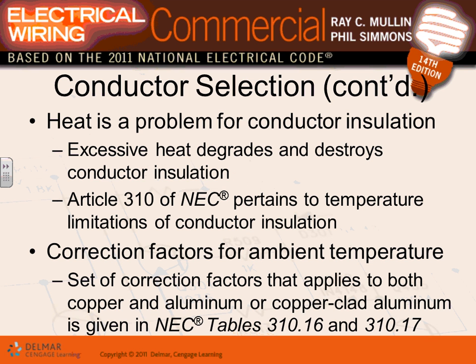That's why excessive heat will destroy your insulation. That's why the NEC code book does a couple of things. Number one, it limits the amount of current that the conductor can carry. And number two, if you put it in a higher temperature, you degrade it again. So it's all about not allowing the conductor to carry more temperature than it can handle under that specific condition, meaning inside the conduit with other conductors, or in very high temperature, higher than 30 degrees Celsius, or on a roof of a building where it could be cooked by direct and indirect heat, the whole derating we talked about.